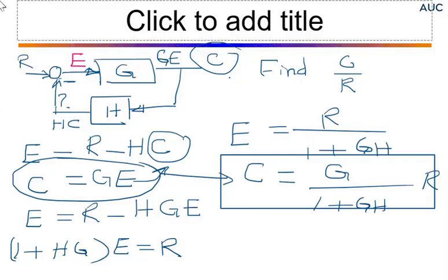You can see here that you have a negative feedback, and the sign that appears here is positive. I'd like you to repeat this derivation, assuming the signal here to be positive, and you will notice that the result will be a negative sign in the denominator here. So do it yourself.